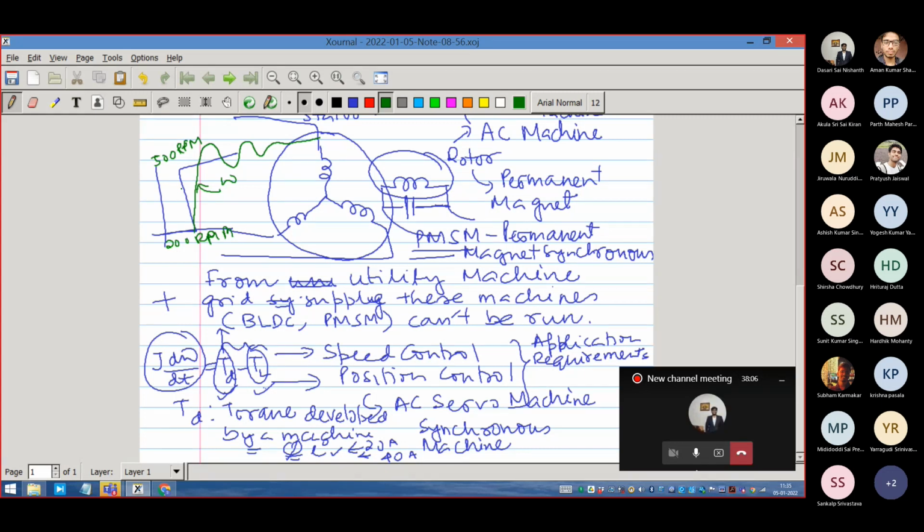The electrical system's job is to produce torque. How does it produce torque? By a product. Product of what? Flux and current. So the flux of the machine and the current of the machine interact. Maybe there is some angle between them, delta being the angle between the flux and current. Then you put in sine delta. So this will be producing a torque, right? Don't bring any other complication. Your mind should be extremely clear that there is no other complication here. I should only focus on flux and current, nothing else, and that is the torque.